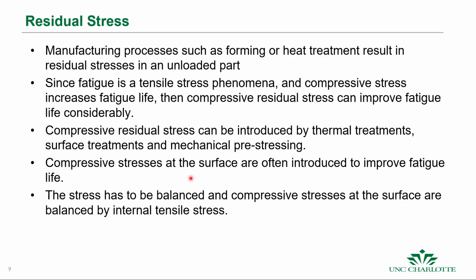But that's not necessarily something that we are as worried about, because the fatigue failure mechanism starts with cracks at the outer surface, not usually inside the part. Okay, and those outer surfaces are often where the stresses are the greatest.